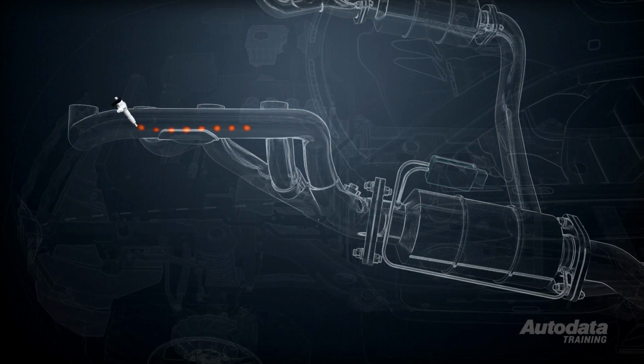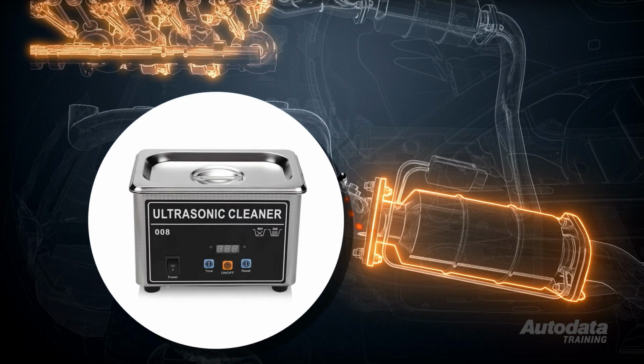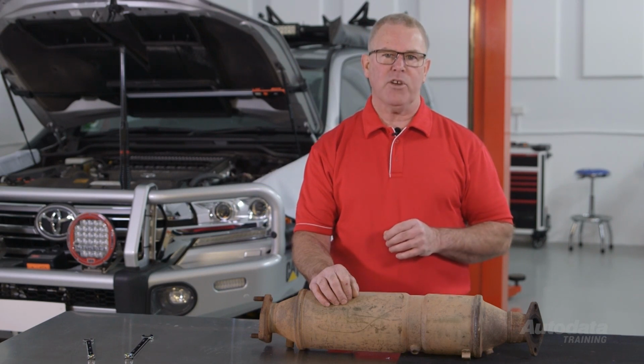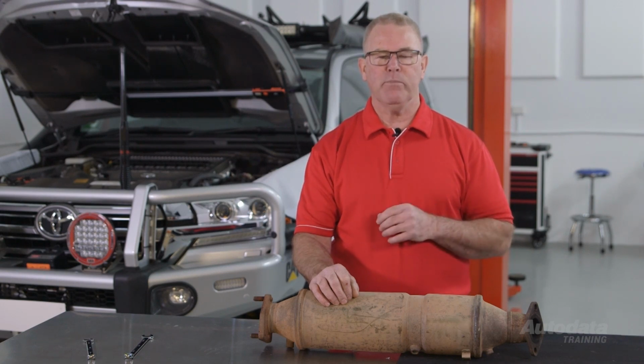DPF regen injection systems need to be cleaned frequently. These are the ones after the cylinder head and before the DPF. An ultrasonic cleaner works best. And remember, if the DPF has been subjected to high levels of ash or repeated regeneration requests have been ignored, it can't be cleaned and will need to be replaced.